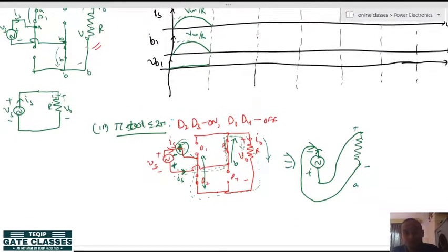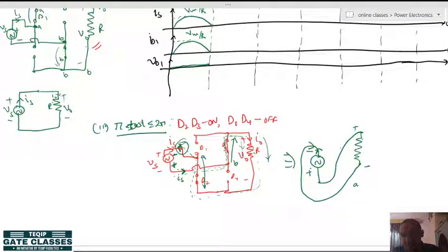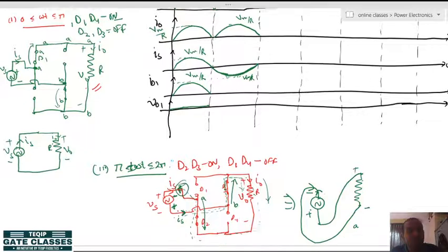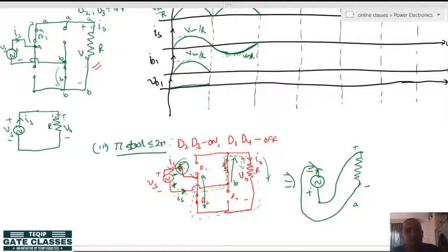Source current and load current are both in series, you can see that they are the same. So, whatever load current is there, that will flow in the source, but on the negative side. Okay. So, it is flowing on the negative side. So, same here it is also Vm by R. So, here also it is Vm by R. And now, if you want to trace diode 1 current, here you can see that diode 1 current will be 0, because diode 1 is off.